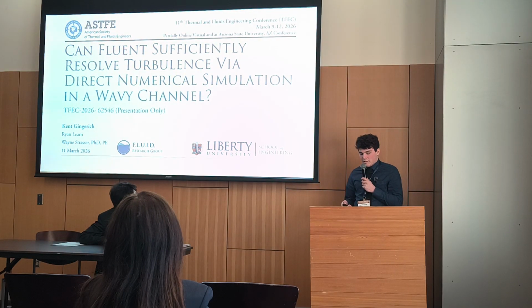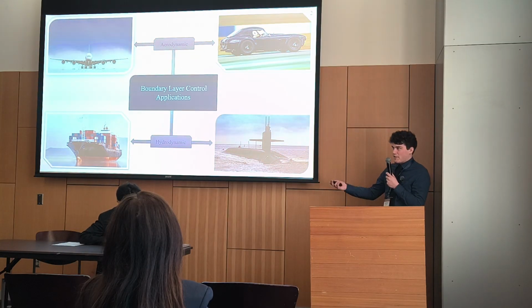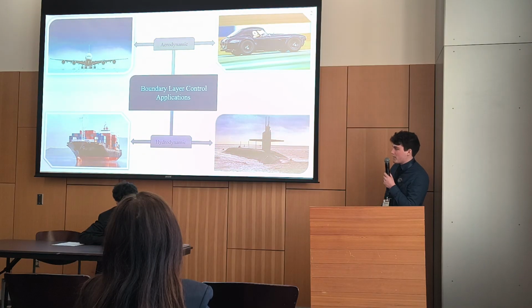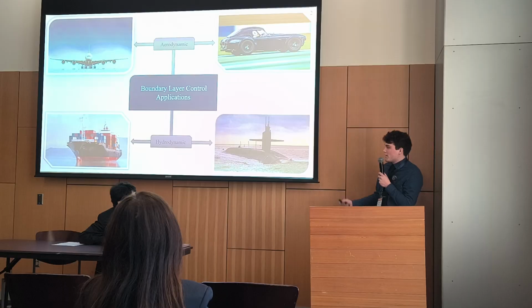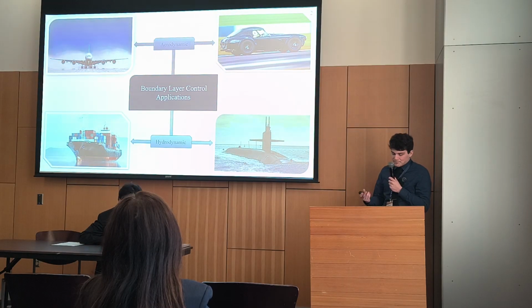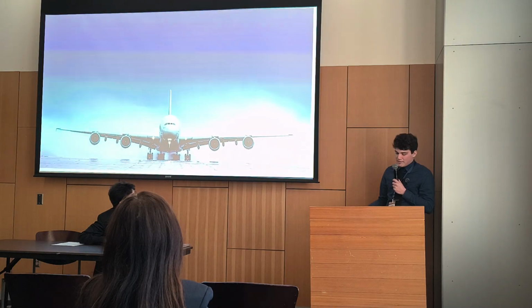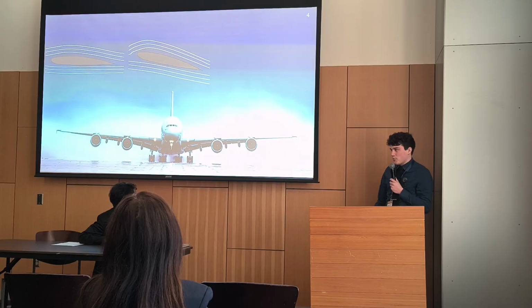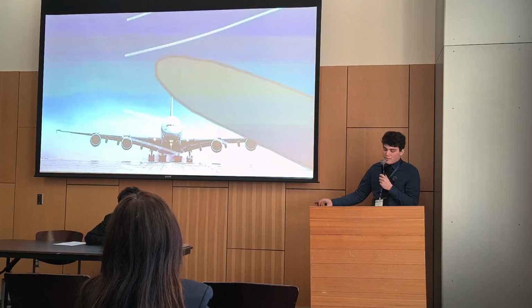We're studying boundary layer control, and some of the applications are both hydrodynamic and aerodynamic: airplanes, race cars, subs, ships. For example, we're just looking at an airfoil on an aircraft. As the airfoil increases its angle of attack, flow is going to separate, and the airfoil stalls.